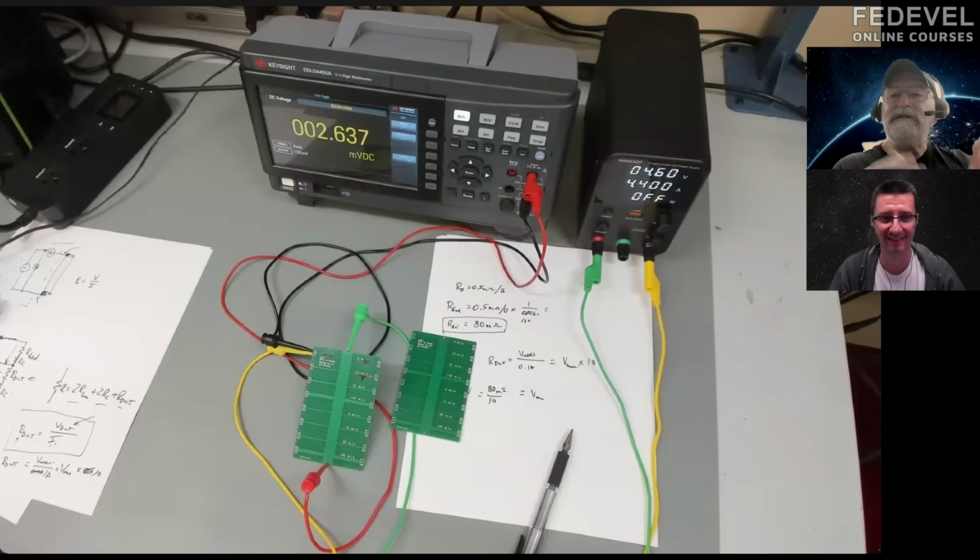And they are using the 4-wire Kelvin method, so that the voltage across that resistor is related to the current, the current times the resistance, and you're not subject to lead resistance or contact resistance in that sense resistor. So it's a very powerful technique to use a small resistor to measure low currents.